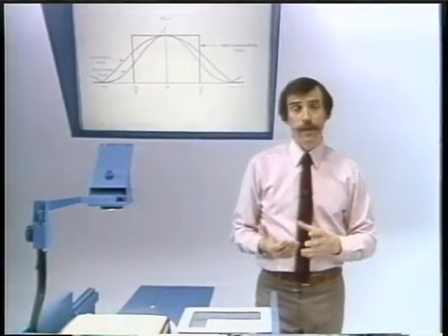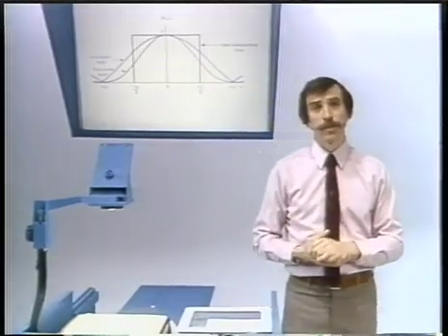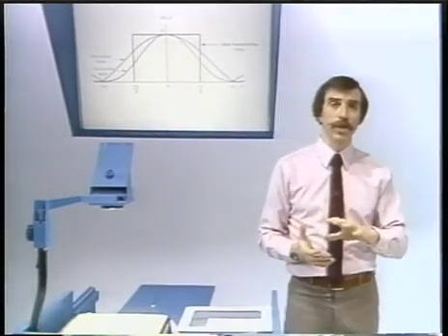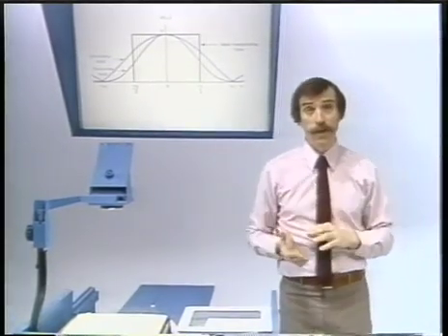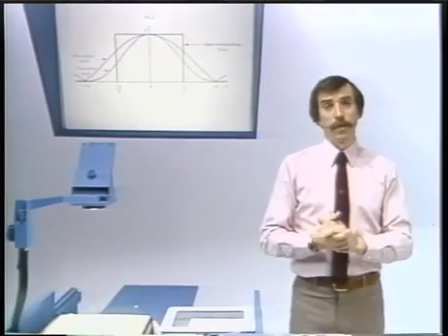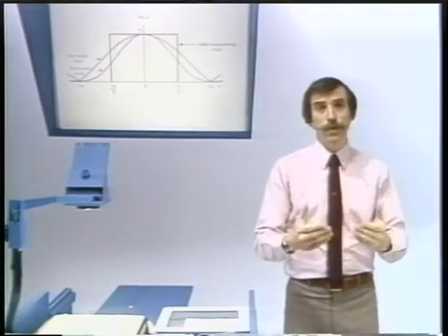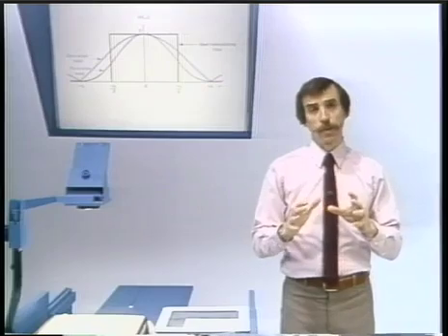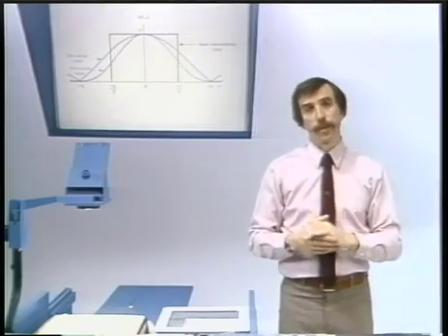Now, in fact, in many sampling systems, in any sampling system really, we need to use some approximation to the low-pass filter. And very often, in fact, what is done in many sampling systems is to first use just a zero-order hold and then follow the zero-order hold with some additional low-pass filtering.